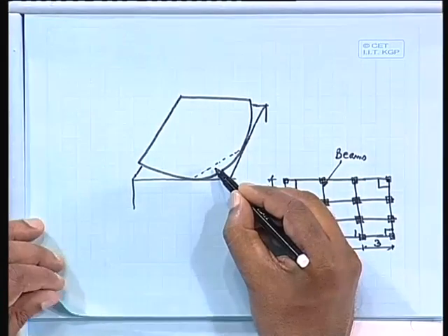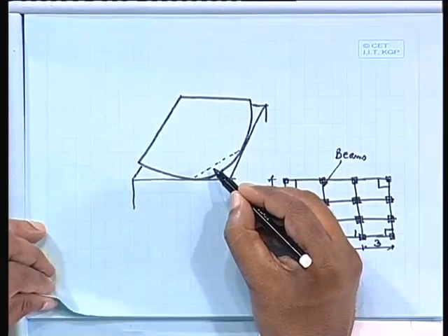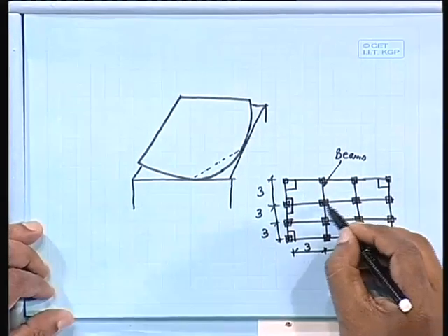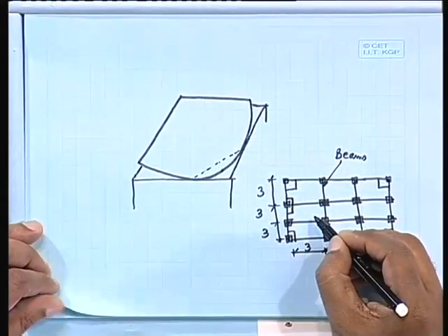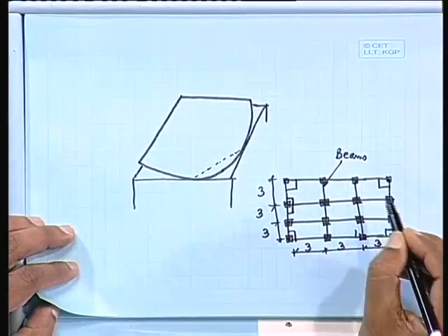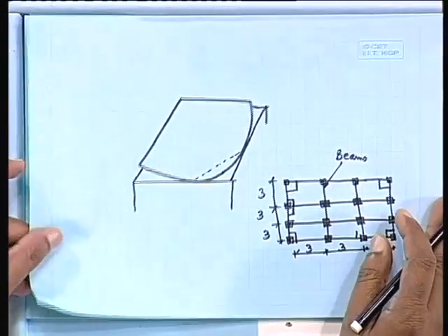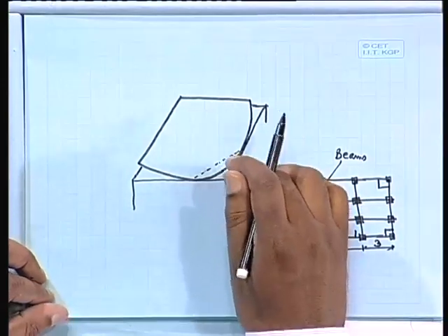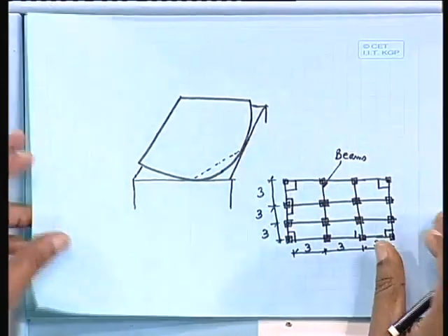So, to overcome that crack we provide the reinforcement in these corners, whereas in the continuous one, since it is balanced by all four sides, there is no need to provide that corner reinforcement. So why should there be a crack? It will lift, yes, it will lift, because of that at the bottom also tension and compression at the top will happen and that's why you will get that crack.